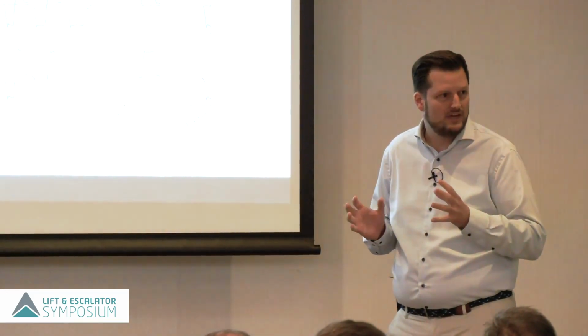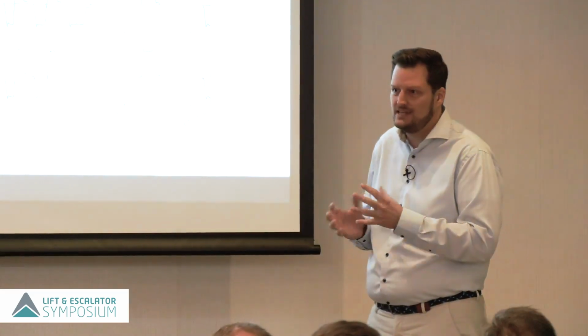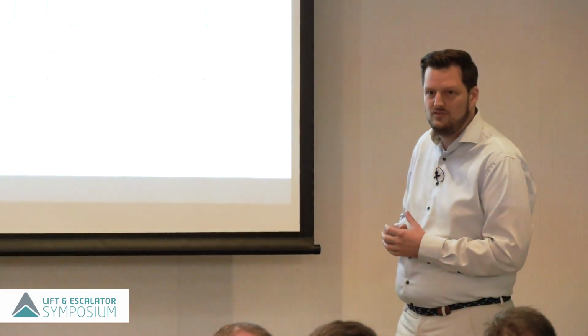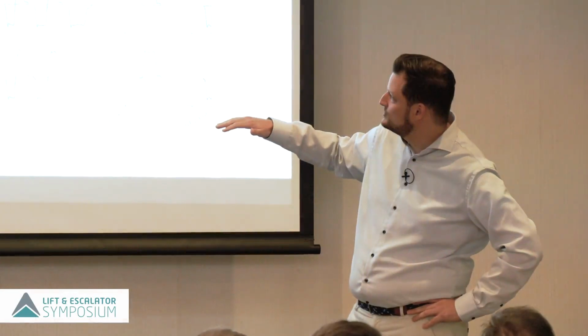So there are some things there. Would it be noise, would it be specific to how this lift door is supposed to operate, is it something else? You cannot exclude it if you don't know what it is. If you have a very slow start or a very slow stop, as you can see those curves when they go from the top to the bottom, straight lines, it's not so smooth of a curve, so we don't quite know what that is. So let's lay over that accelerometer data in meters per second square.